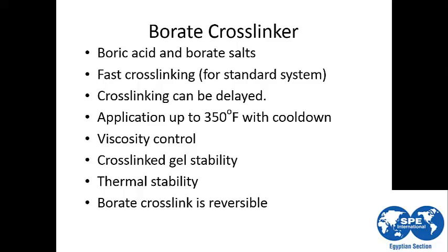It can crosslink up to 350 Fahrenheit with cooling down. Cooling down means pumping water in front of the fracture fluid, to cool down the reservoir rock before starting to pump the pad, so we can reach this 350 using the cool down water.